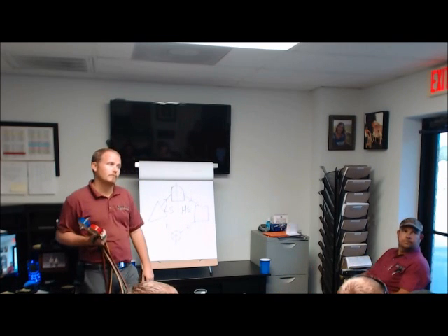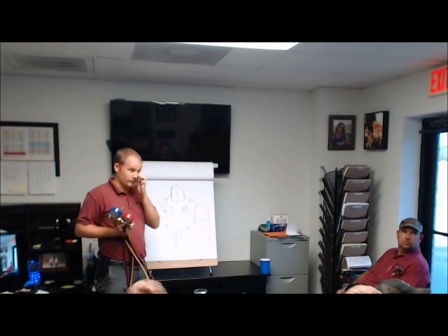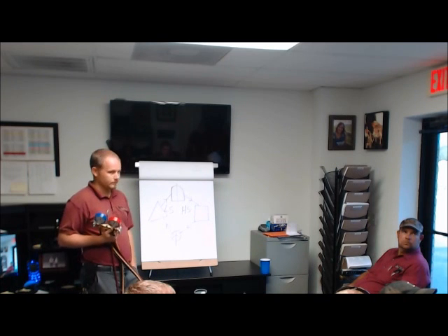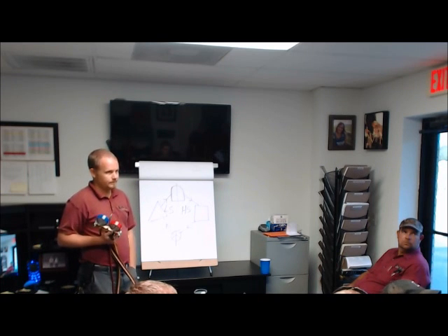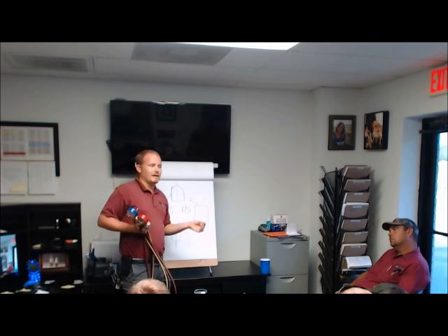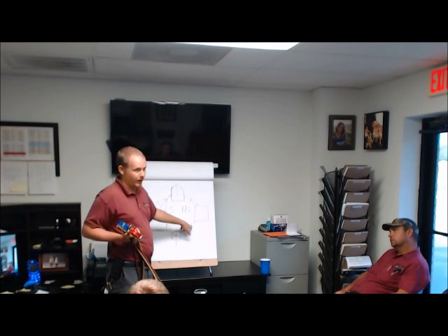Now, if you just get out of this room and go to a pool heat pump, and you're looking, it's the same way though, right? Because a lot of times your high side is actually your discharge line on the pool pump, depending upon whether it's before or after. Correct. So practically speaking, here's what happens. You're going to be taking your pressure here and your temperature here. So that will affect it because you are going to have pressure drop.